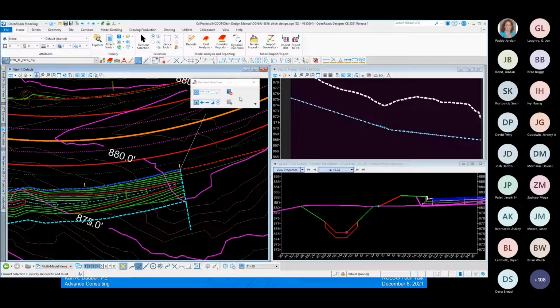It's not doable. They're two different lengths. If you had a horizontal curve on the inside and outside, those are different lengths. So even if you restation the start station to match roadway alignments, your inside and outside slope stake will be different stations when you enter a curve.